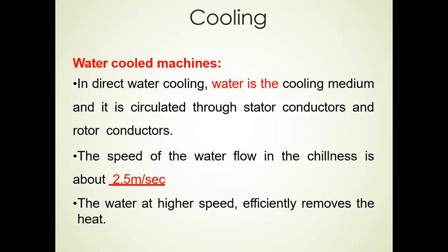So it may be of radiation, convection, and conduction. The movement of coolant is by temperature differences. The fanning action of the rotor is negligible. That is in the case of convection. Okay, it is totally free. Self-circulation: in the case of self-circulation, the movement of coolant is either by a fanning action of the rotor alone or by means of a component designated for this purpose and mounted directly on the shaft of the machine. The circulation by integral dependent component is by means of an integral component not mounted directly on the shaft of the machine.